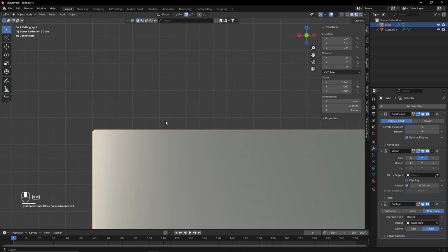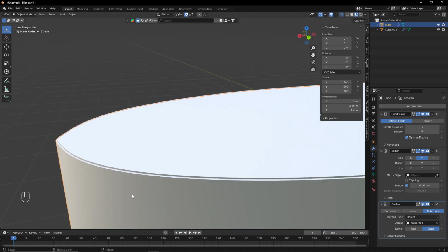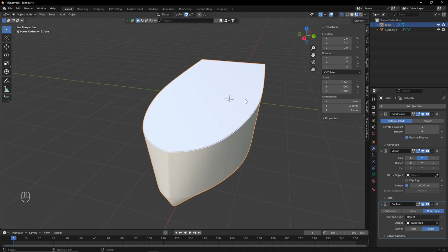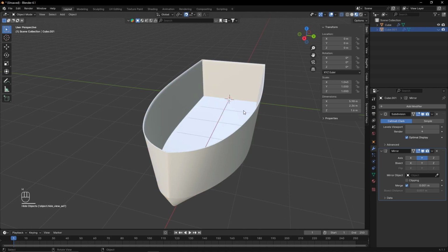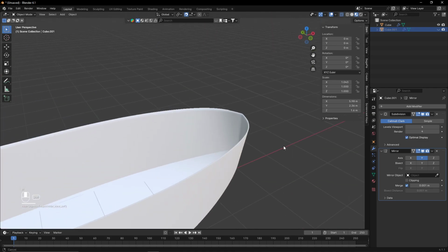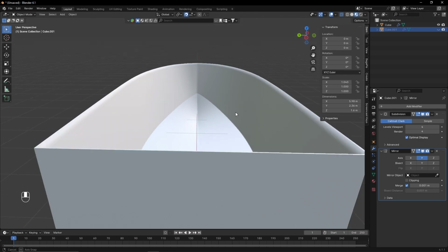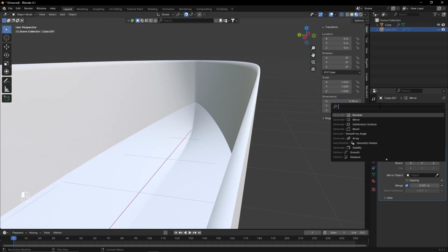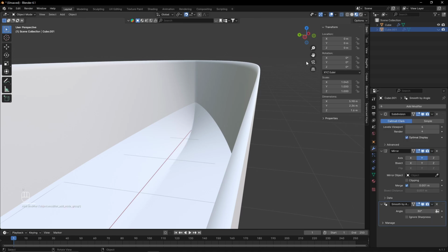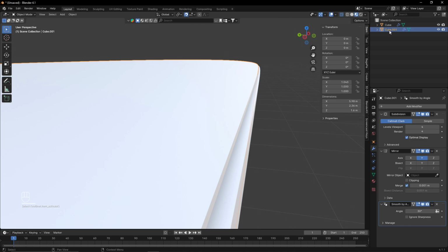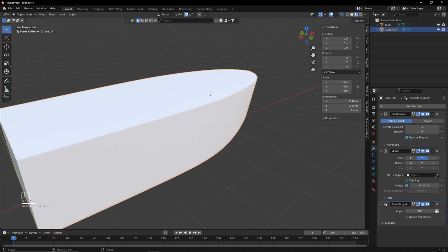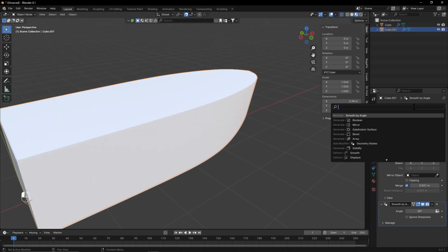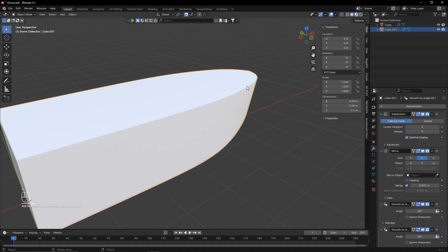Here, by using a difference from our basic hull to our slightly moved inward hull, we can get this. And in the new version of Blender, you've got that small geometry error that appears. The way to fix it is to go Smooth by Angle. And same for the minus hull in the Boolean difference. Smooth by Angle.